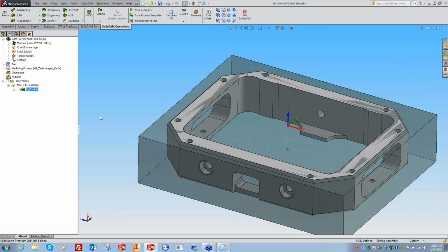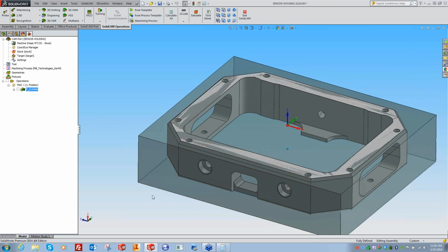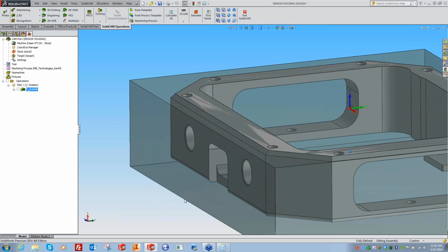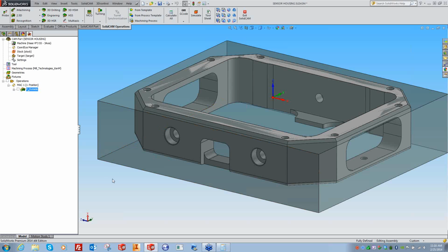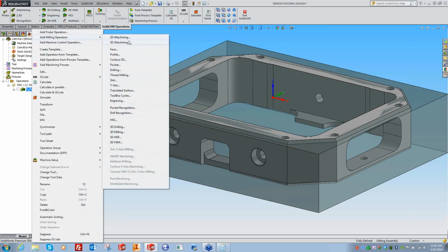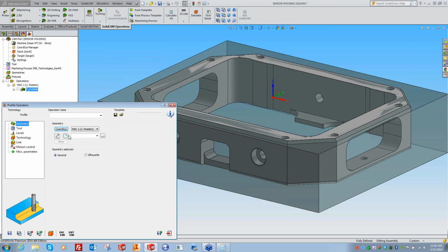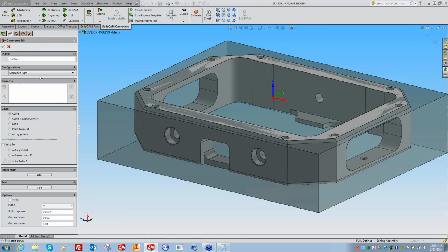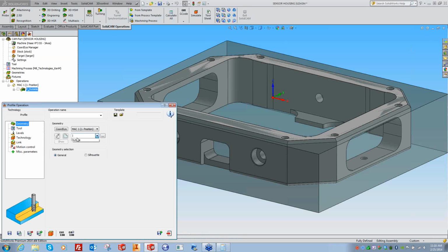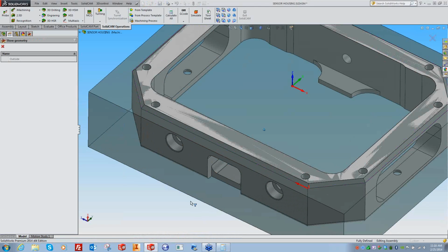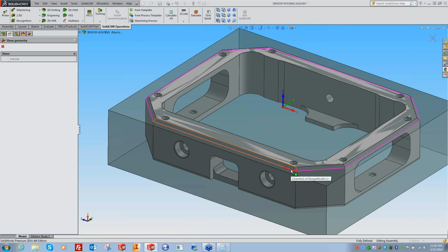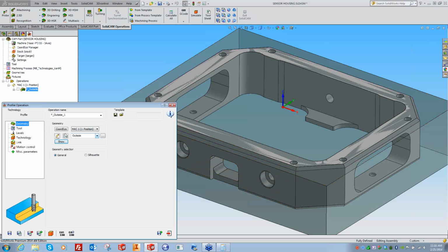Let's go ahead and do our chamfering operation right here. Now that we've roughed the outside, we're going to go ahead and do this chamfer operation. You can do that in pocket mode, or you can do it in contour or profile mode. We're going to do another profile. So grab our profile, which actually is the same profile that we're going to be using from the outside of the first one. I think it's easier if you select the bottom edge of the chamfer, and since that's the one I selected before, I'm just going to use the same profile.